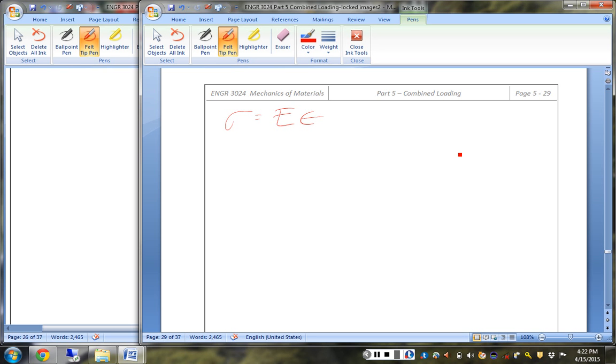So you're going to have an X component and a Y component, and your stress is going to be acting in both the X and the Y. Right, but in our force balance, we only talk about the X direction or the Y direction, so it still resolves out. But yes, because of that hemispherical shape, it's not just in the X direction. That's absolutely true.